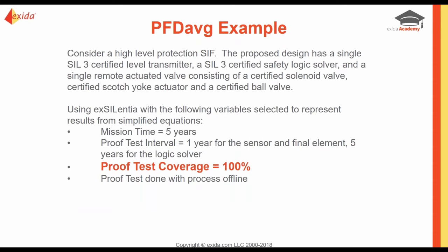I promised you examples, so let's look at some. So here, let's consider a high protection SIF. It's a SIL3. We have a single SIL3 level transmitter, a SIL3 logic solver, a remote actuated valve, a solenoid, Scotch yoke actuator, certified ball valve, all certified to SIL3. Great.